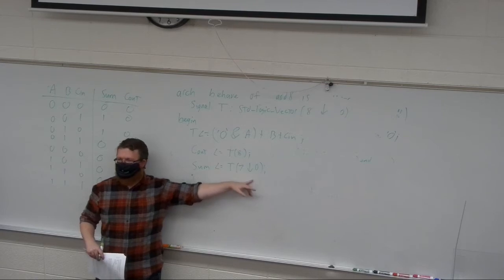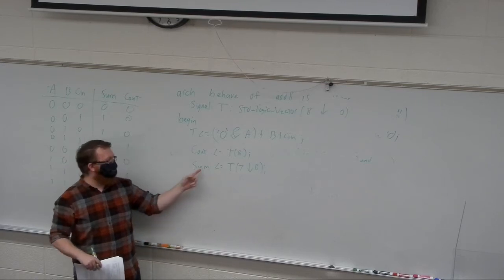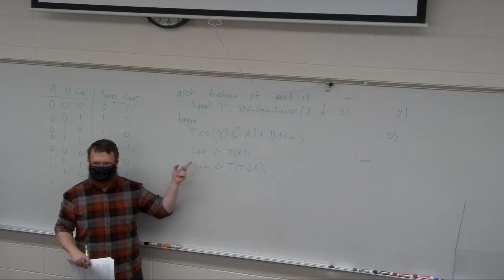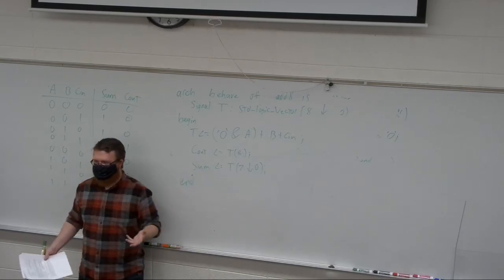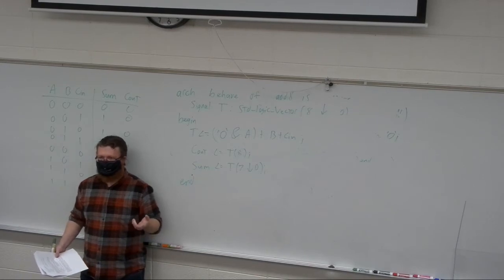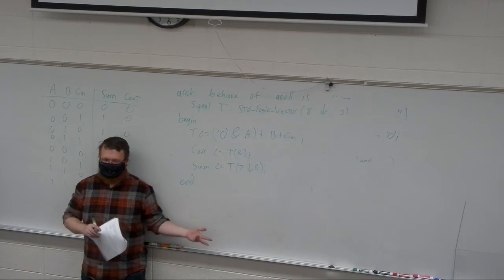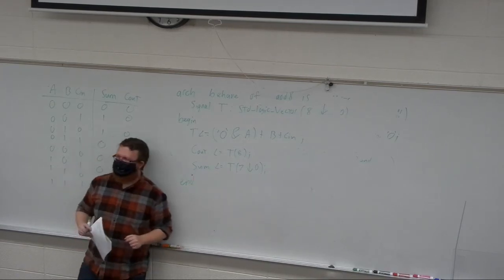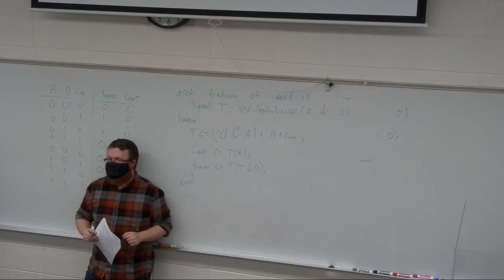There's not really a difference between having a 9-bit sum instead of a sum and a carry out. Either way is really quite okay, because it's the same thing, right? A carry out has the same value as the 9th bit of that sum. Any questions on that?